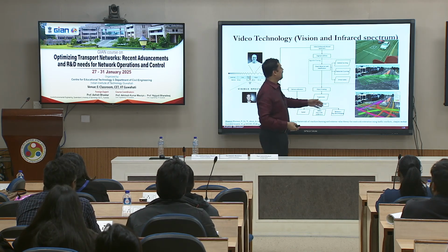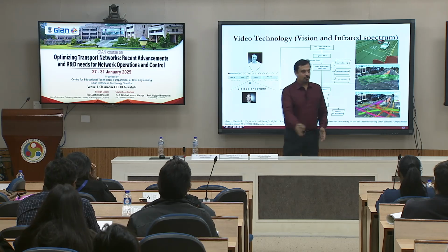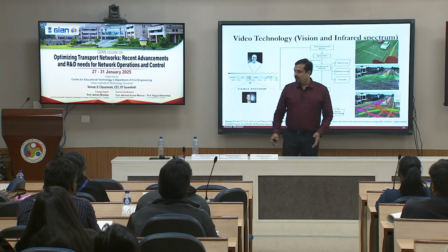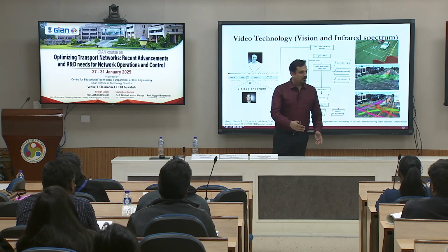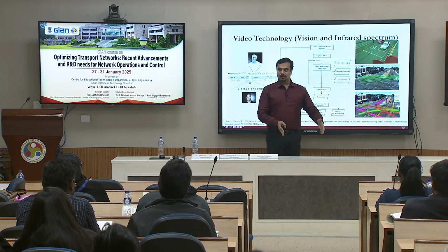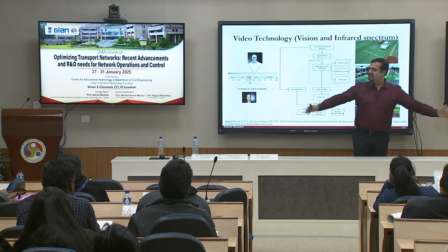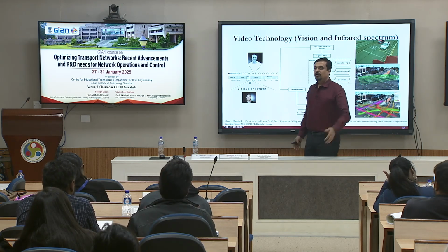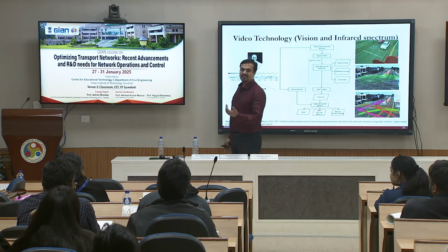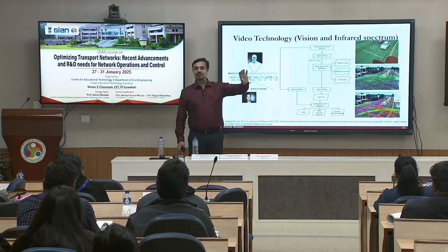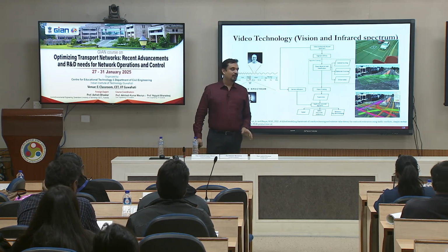Let's say this is the entire corridor with this intersection, that intersection, and there is a bus stop here. You know the GPS coordinates. Let's say you have detailed coordinates. You can take the impact of that bus stop away based on the time it arrived and left, and you can get the average running speed along this one. During congested conditions, the other speeds will be certain. There will be some correlation. So the higher the bus travel time, the higher your car one.